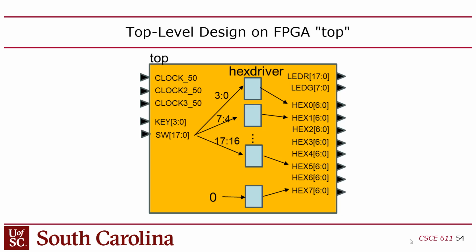There's also a key input. The key input are the buttons. There's 4 buttons. You're not using those for this lab either. We'll use that for the reset in the next lab. And then the switch, obviously we'll use. The switch input is an 18-bit signal. It will have to be fanned out to your, well, not fanned out, actually. It should be split into different bit ranges to your hex drivers.